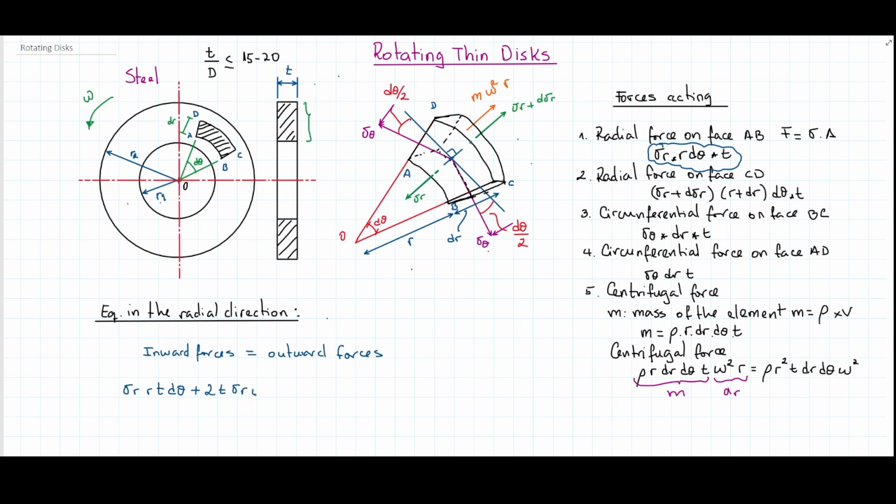I'm going to try to write things. Sorry about that. t dr σ_θ times the sine of that angle there. And that's going to be equal to what is left here, which are basically two forces. One is the centrifugal force, and the second one is related to the radial stress plus the increment or variation of that radial stress on that surface. We have tackled this one already, so we're missing this one, and let's write it down.